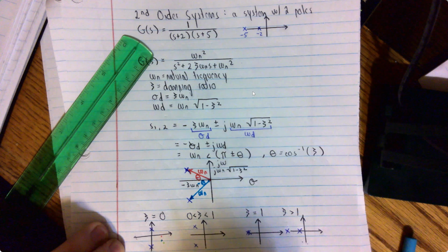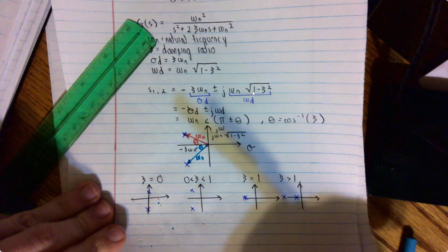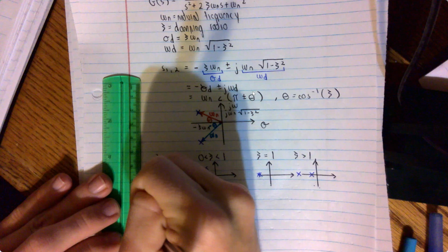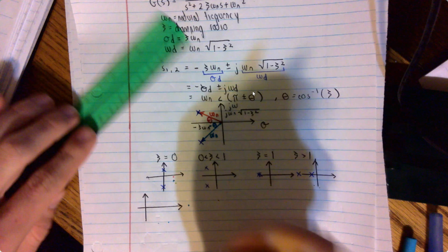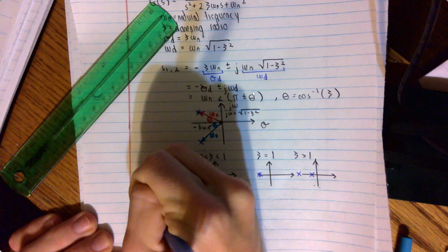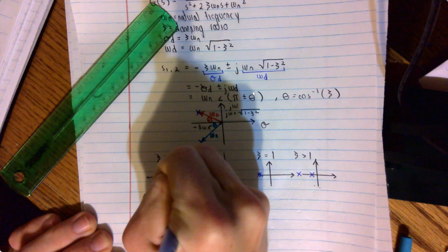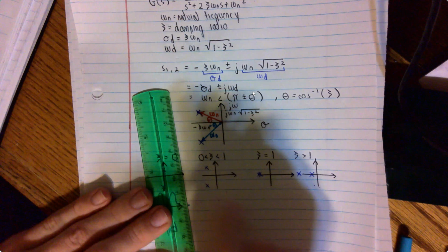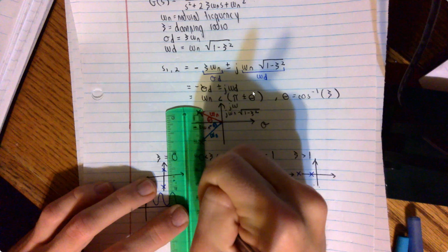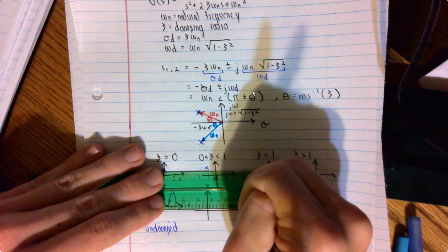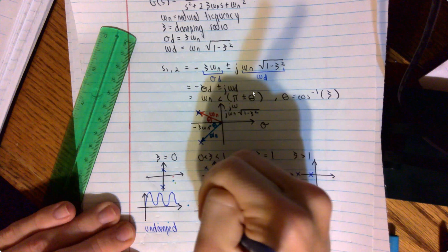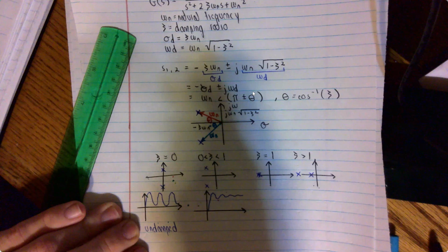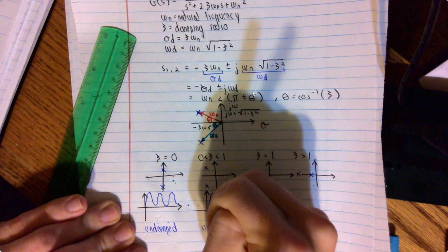And so this response, when you're on the imaginary axis, is completely oscillatory. So notice that we have an oscillating waveform. This is known as undamped. Where we have the poles in between, this is going to be our underdamped. Looking at the response, notice it's going to oscillate at the beginning and then slowly die out. So this is known as underdamped. These oscillations start to decrease over time.